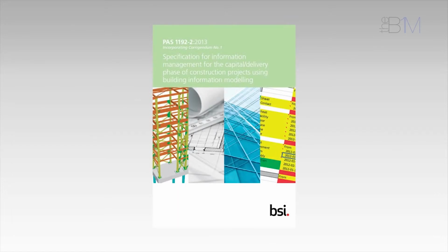A common data environment can take on many forms depending on the size or type of project you're working on. It could be a project server, an extranet or a cloud-based system. The important thing is that it's digital, that everyone in your team has access to it, and that it can be easily subdivided into areas. It needs to be a collaborative and well-managed space for sharing work. Here, we're going to look at the Common Data Environment format as set out in the British Standards PAS 1192 Part 2, the guidance document for delivering projects at BIM Level 2.